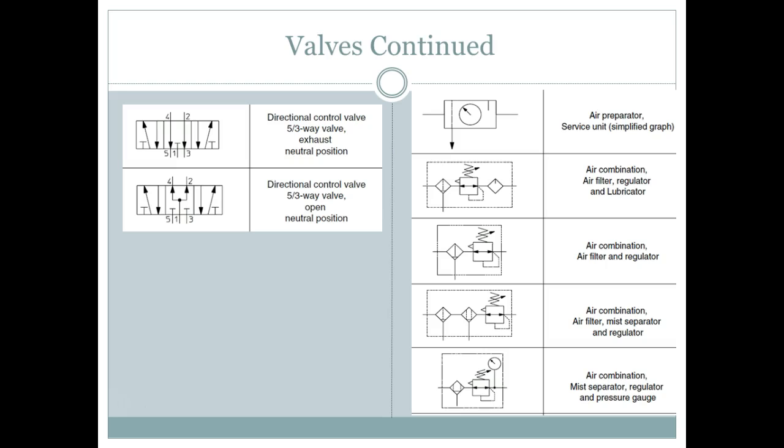If you didn't have a pressure regulator and couldn't set it to 60, what would your air tool see? It would see something between 70 and 100 psi all the time. And what would happen? It'd wear out or blow the seals out of your motors, right? So a lot of the compressors that we'll use are cycling compressors.